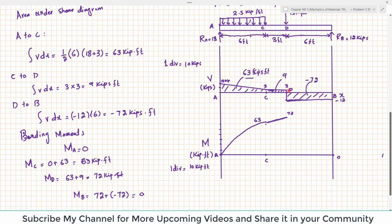And from D to B, again, this is a zero degree line or constant line with zero slope. Since it is negative, the slope will be downward there. So it will be a straight line like this. This is point D. So this is your bending moment diagram.